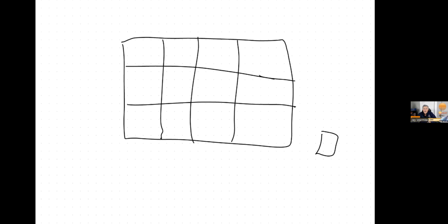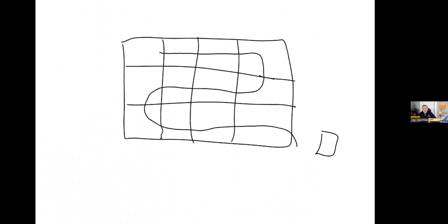If I was wiring these panels together in a string, going from negative to positive, hooking all these panels together and then it comes down to hook into my inverter, all of these panels now behave as a unit, and they're all connected to just one MPPT.